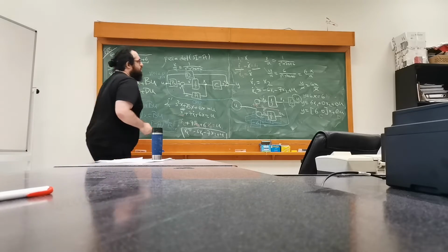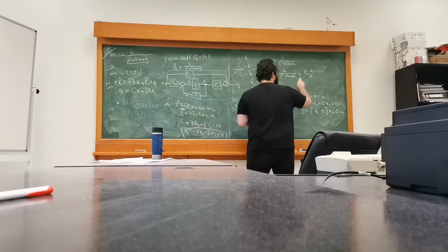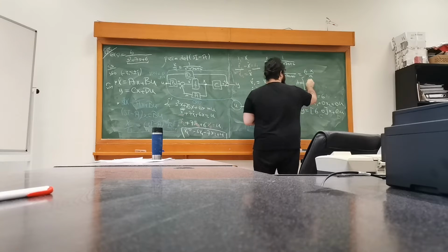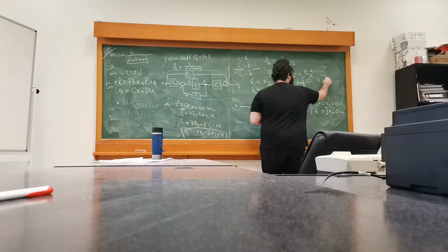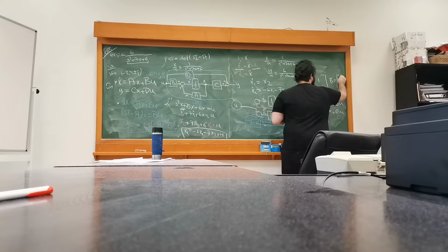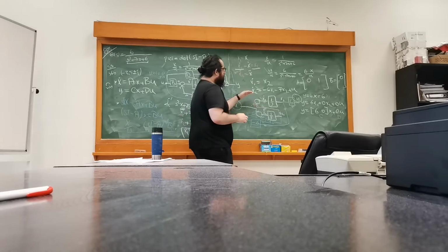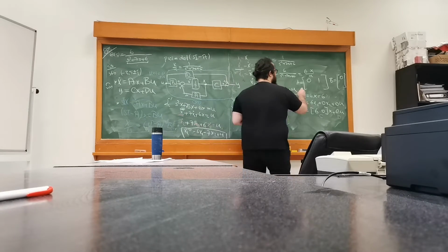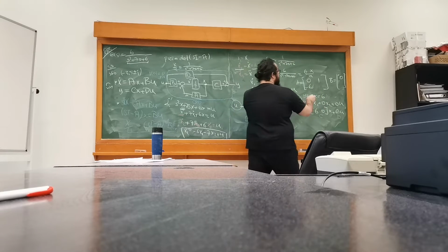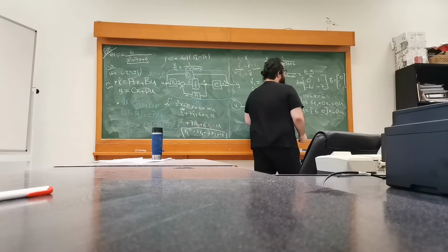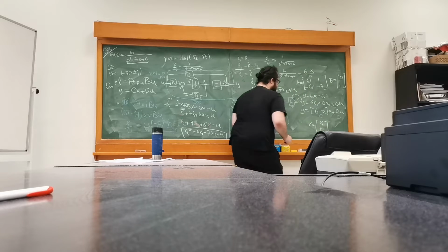So, of course I didn't write down what A and B look like, so let me get rid of this part here quickly. So the A matrix here is 0, 1, because 0 times x1 plus 1 times x2 plus 0 times u is the first equation here. So the first row is the first equation. Now for the second row, I have minus 6x1, the first one is x1, so minus 6. And minus 7 is the second one, and 1 is this one. Of course, x in this case is defined as x1 and x2.